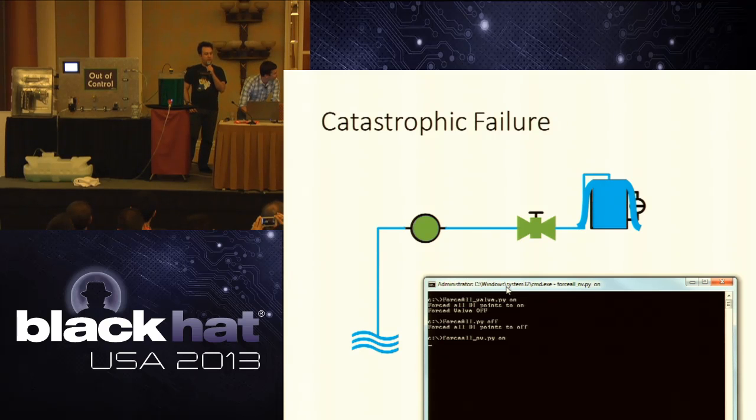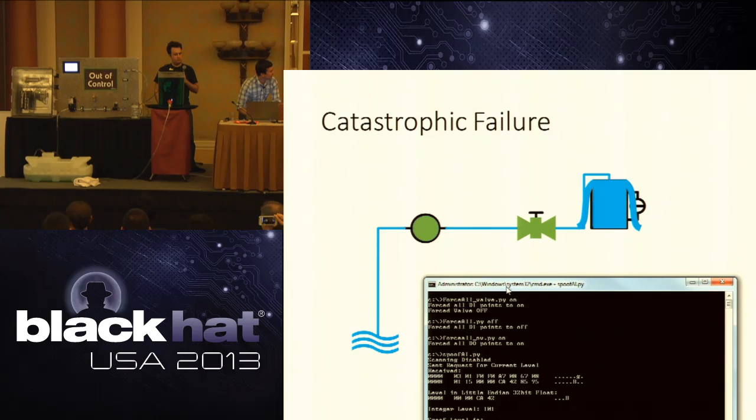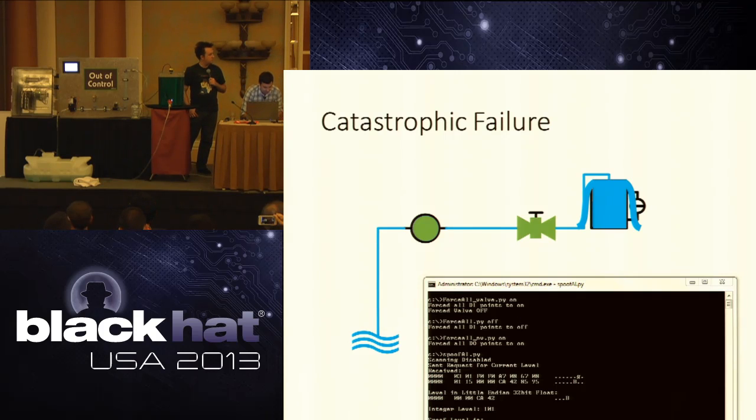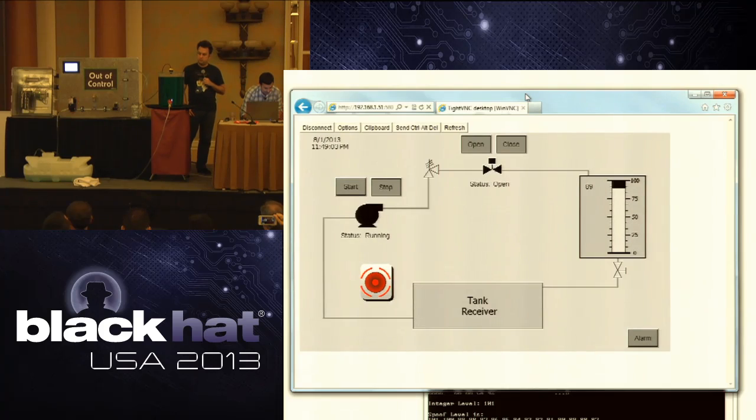Okay, so we'll give it a shot. We'll see what happens. So what we're doing is we're iterating through every Modbus point, that's why it's taking a little bit, and just turning them all on. Okay? But what we want to do is actually tell the PLC what to think. And we can do that.